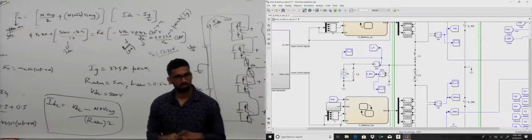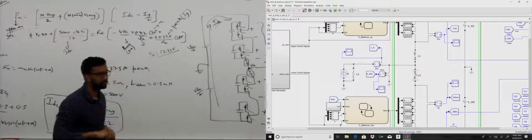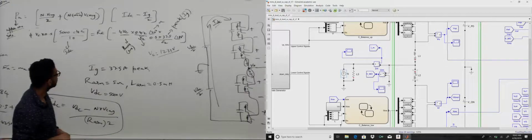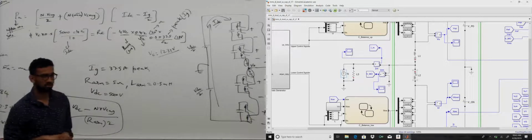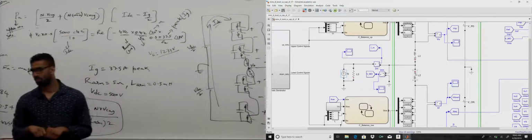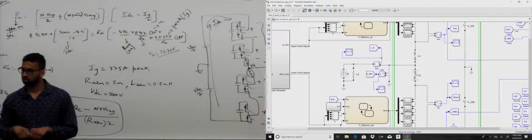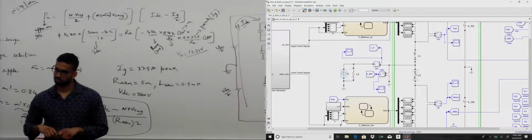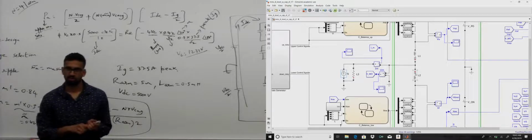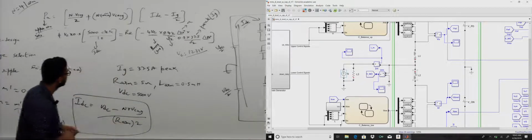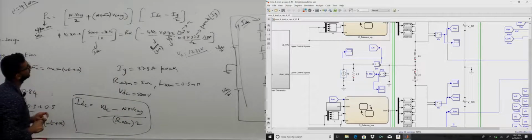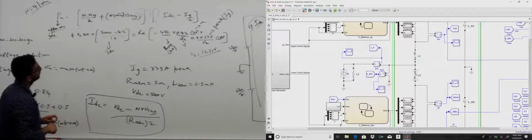Just one clarification. This is for one phase, right? So that's why it seems like it has large ripple. But in three phase, the three phases are offset, so they cancel out and you get DC on the DC side, right? But if you stay with this single phase circuit, then you have large ripple, just like in a single phase rectifier, right? Yes.